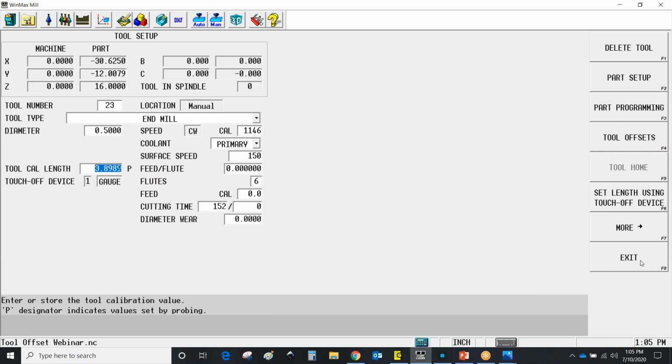One of them is fine, the other one is running a little bit shallow or a little deep. I can't make one offset that won't, because if I make just one offset like here on the tool length cal, it will change one and affect the other as well. So that might be an instance where we would call a G43 H23 and an H123 or something like that. So there are specific reasons why someone would want to use those.